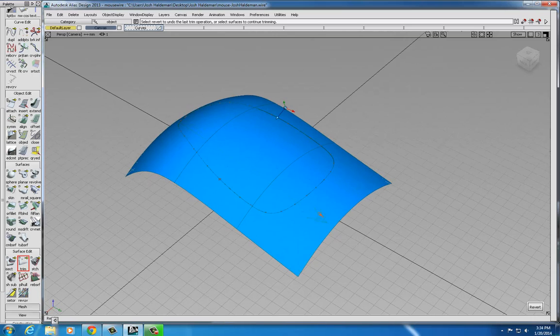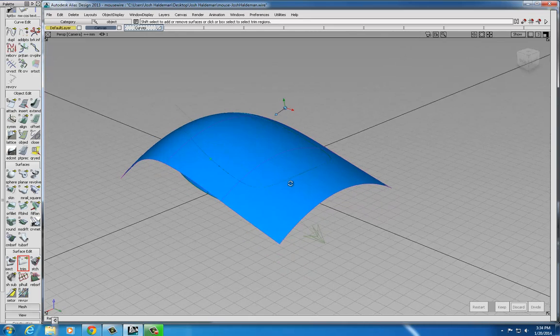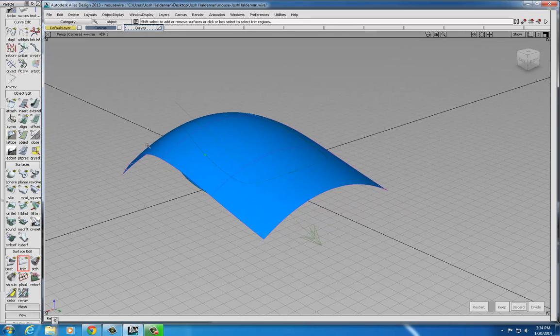That next step then is to remove this top surface, the excess part of the top. So I'm going to go, and I don't need to reselect the tool. I just need to pick the next surface to trim. And notice that it'll highlight there in magenta. It's kind of subtle. It can be a little hard to see at times. And then we just need to pick a part. Let's do the keep command this time instead of discard.